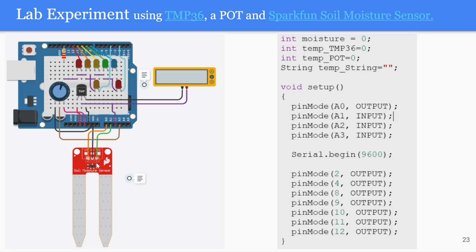And you can see here that it's connected with the ground, an A0, A1 line, and A0 is basically just there to be used as a digital kind of line. As you can see here, A0 is an output, so it means this is just a digital line. Then A1 is the input line where the analog voltages are coming in.